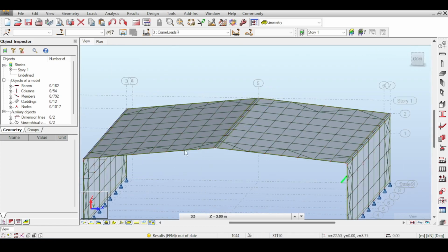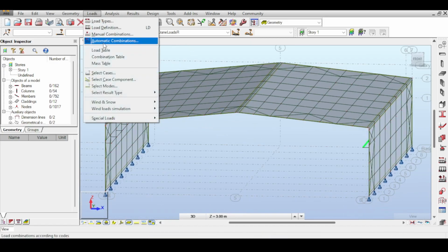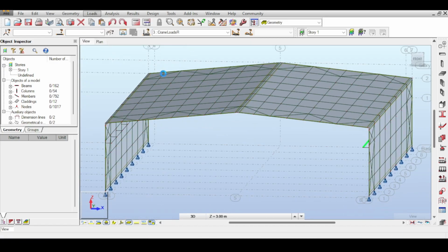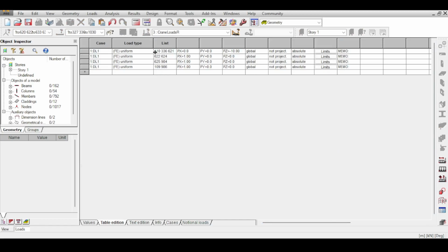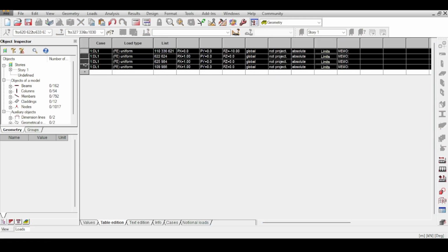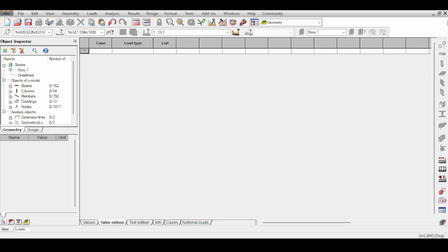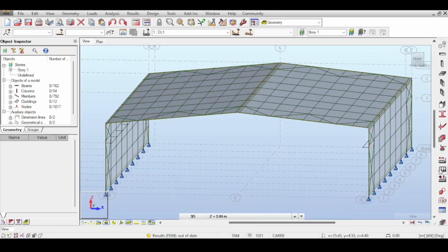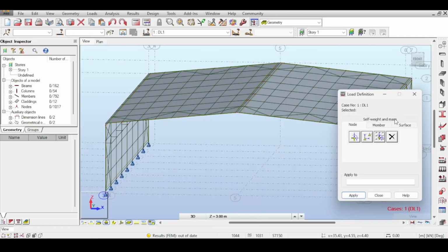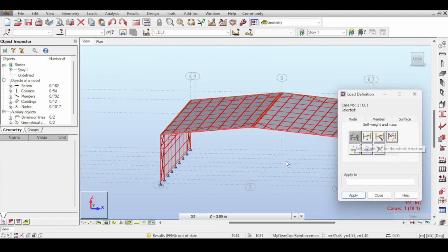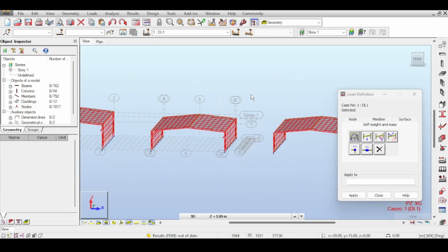What else remains? Well, the own weight I need to add, because I remember in one of those technicalities I removed the own weight. Did I? What are those loads? Okay, oh, right. I remember. Those are the loads we tried during our trial error thing, during our cladding dilemma, right? So I go to member. I'll add self-weight for the entire structure. So now everything has self-weight. Perfect. And now we need to apply dead loads.